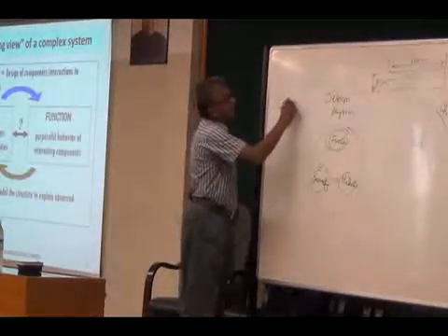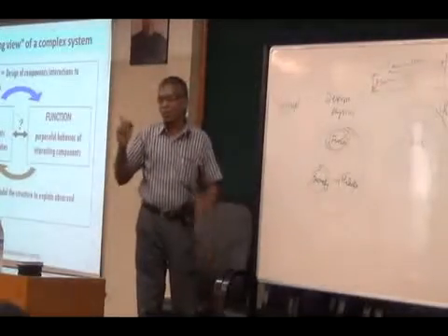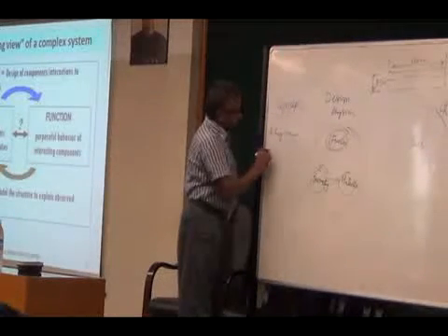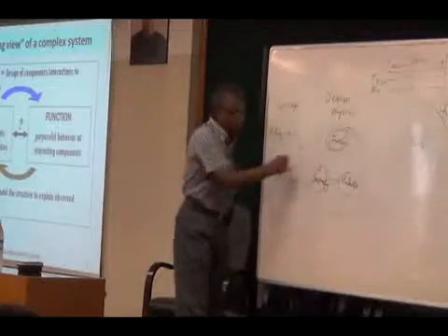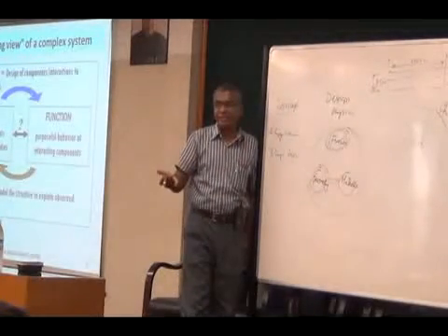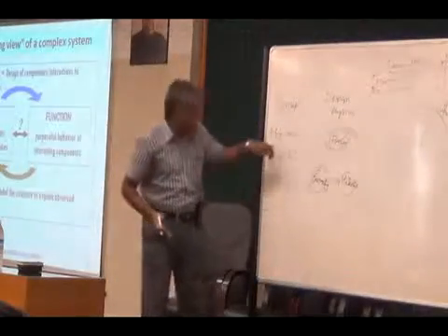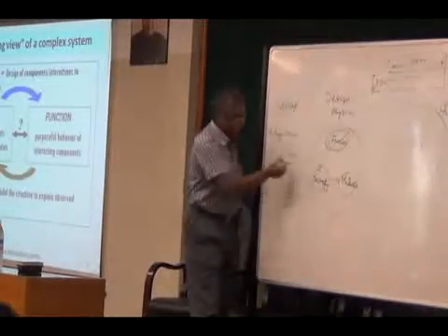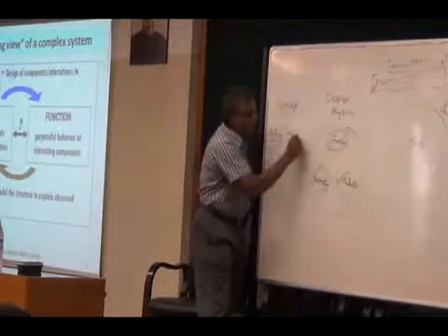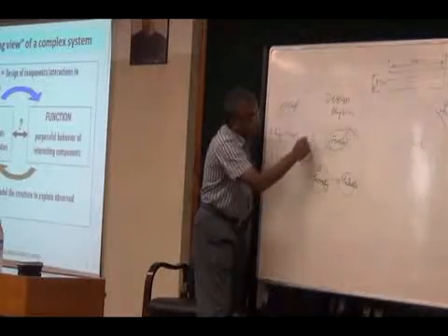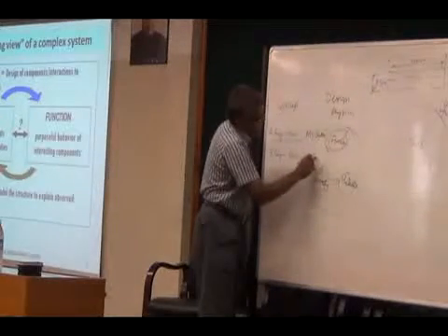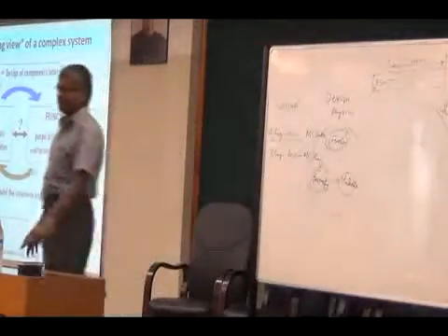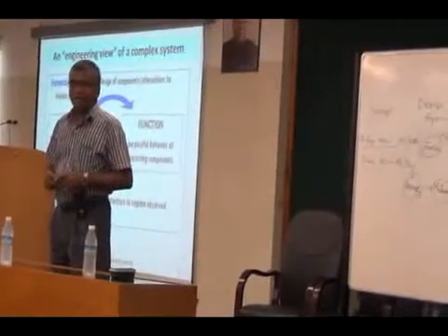Now, what is the concept? Because we are supposed to only understand a concept. Let me give one idea, only for chair. Okay? I got a 4-legged chair, 3-legged stool. Look at this. Function is almost the same, but the secondary function is like stability. 3-leg is less, whereas 4-leg is more. Now, function is almost the same. Geometry is different. Okay, I am giving material. Maybe this is mild steel, or this can be mild steel. Instead of that, you can have plastic. This also can be plastic. So, a particular set of function, geometry, and material is a concept.